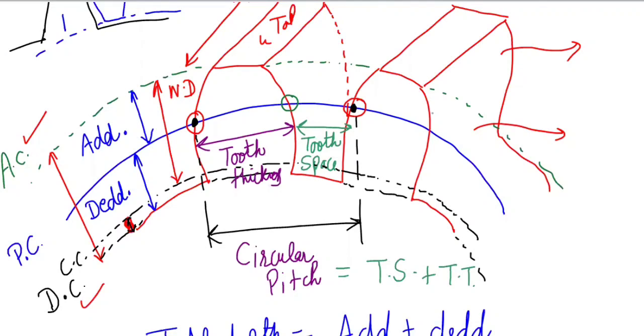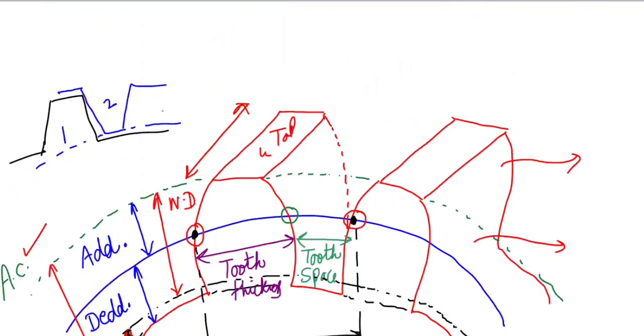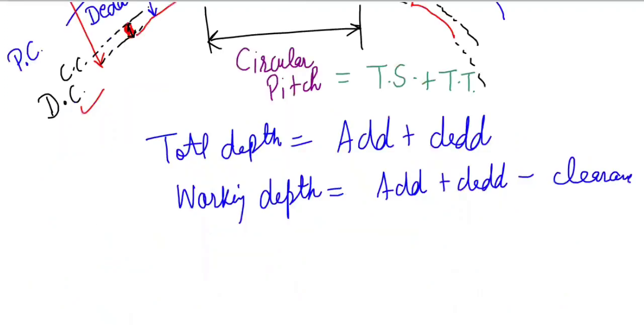So that's why I can say that whenever there is another gear, suppose there is another teeth over here, this blue part can only enter whenever there is this much space, na, Anjali? If this space is not equal to the tooth thickness of the gear number 2, then we cannot say that the gear would mesh or power transmission could happen. So here comes the small definition, which will be widely used in our numerical part.